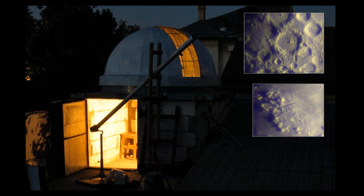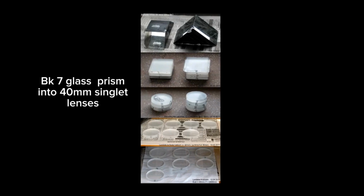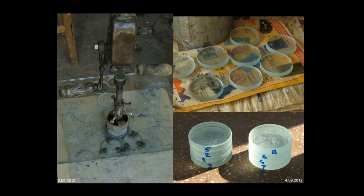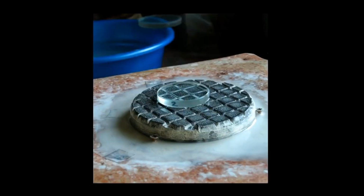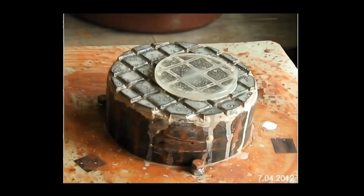Quite good images. Now we're going to talk about the process of making the lenses. He uses BK7 plate glass and also window glass, tested before to see if the glass has some defects. And then he grinds the lens on a concave mirror using abrasive, the same process we use to make mirrors. And then he polishes the lens on a pitch tool, the same curvature as the concave mirror, with cerium oxide.